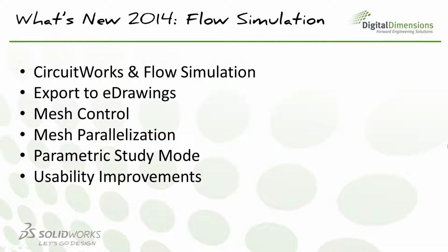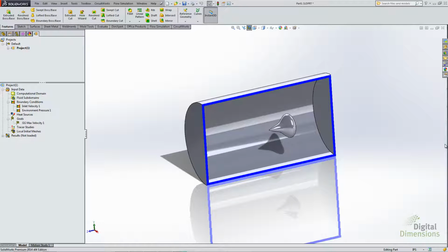Moving along, let's talk about parametric studies. Once we generate a new parametric study, whether it be an optimization or a what-if scenario, SOLIDWORKS will automatically generate a new entry for your parametric study under your project. This improves flexibility with the tool. Instead of having to save and reopen our setup, that setup now exists within our project and can be accessed later on.